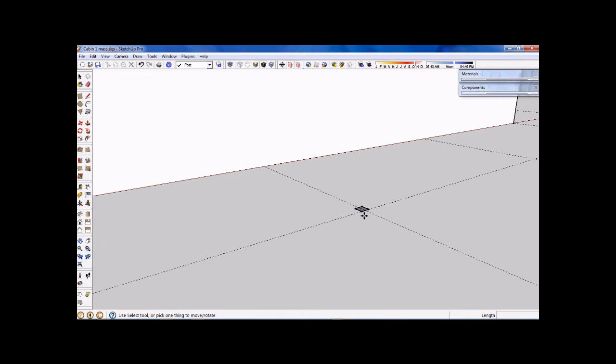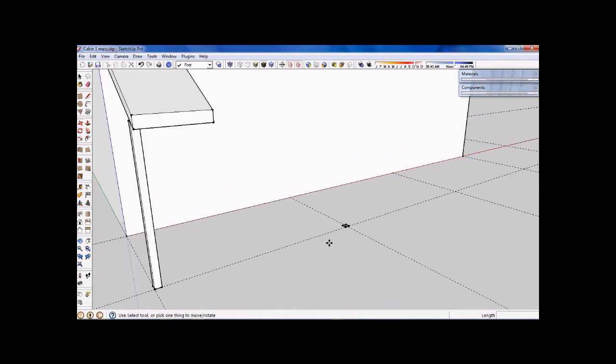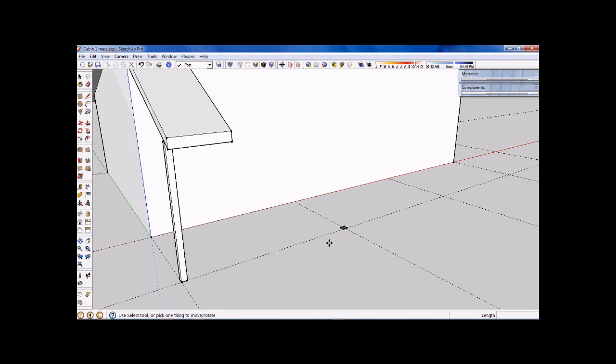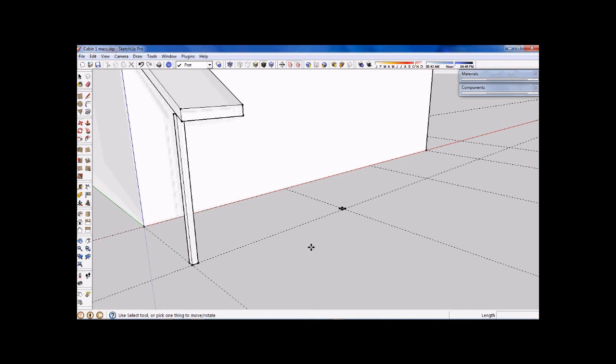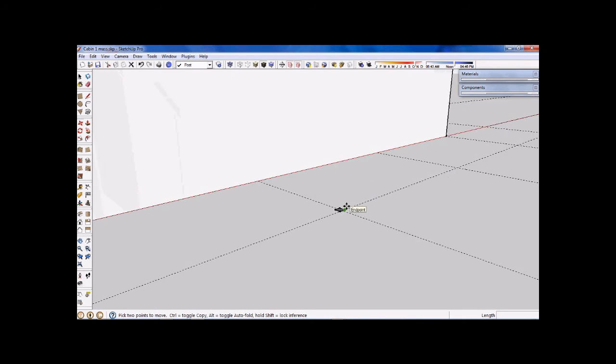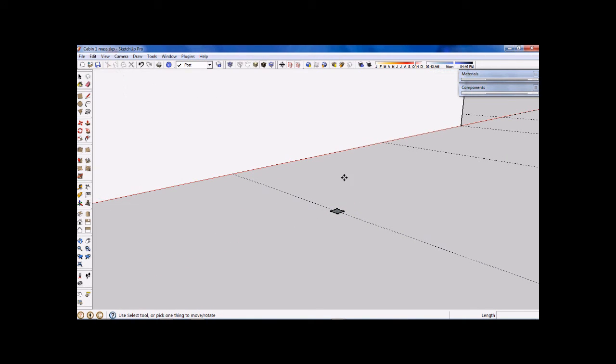My method behind doing that, my logic behind doing that, is that I do want the builder's grid lines, set out lines if you like, to indicate the outside edges of the building. However, in items like this, towards the inside where we've got spaced items, I would like the center of those spaced items to be on the grid line.